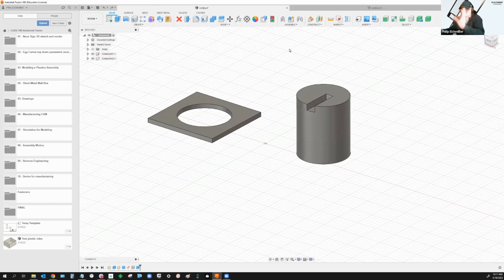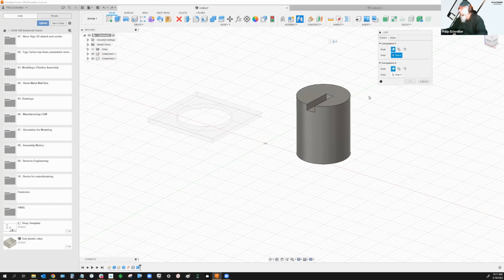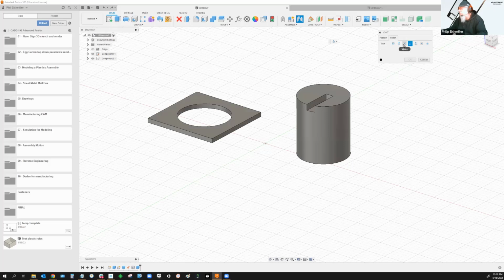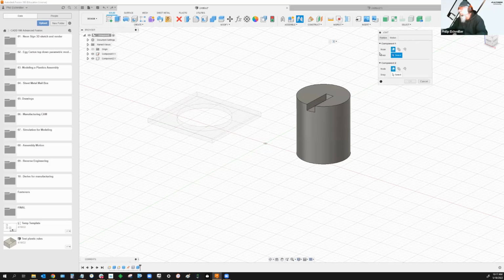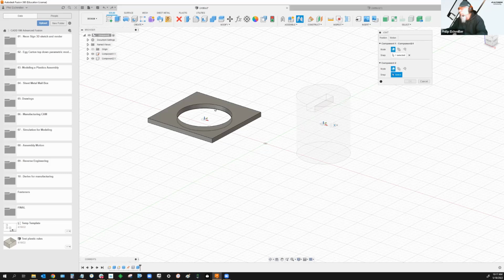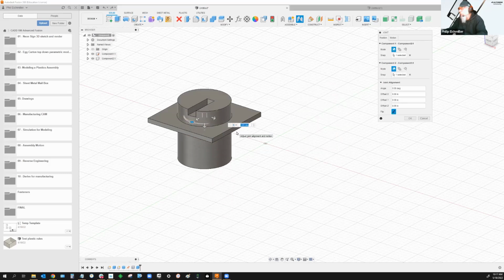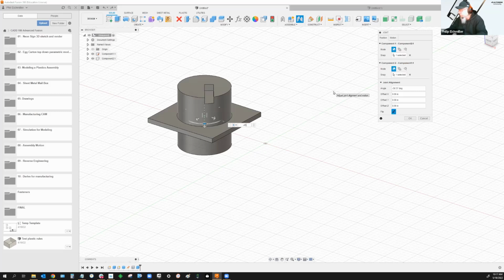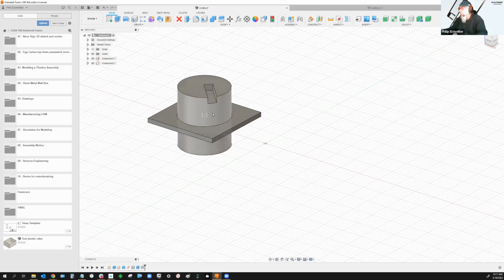Now, if the shaft was, for instance, constrained completely in terms of rotation, and you just want it to be at a specific angle, then I would actually go for a slider and put a slider in here that allows me to set it up and give it an angle of rotation, but it'll maintain that angle of rotation. So a slider has one less degree of freedom than cylindrical does.